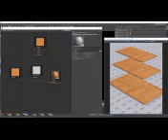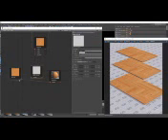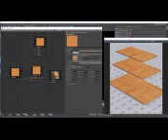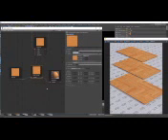In the interactive renderer, you notice because these boxes have the exact same UV, the wood texture has been applied the same way to all of them, and this is exactly what UVW randomizer fixes. UVW randomizer map allows applying random offset, rotation, scale to textures and procedural maps assigned to different objects. So let's add a UVW randomizer and connect the wood texture as the input and connect the UVW randomizer to the diffuse color.